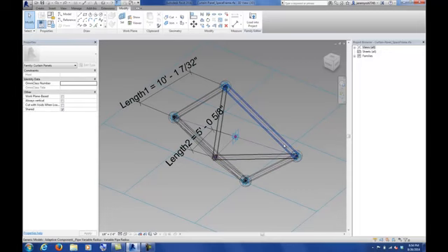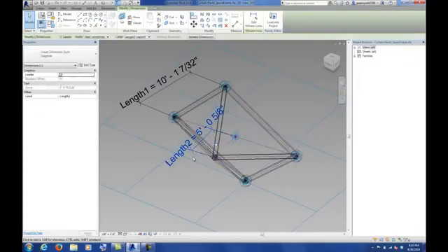All of these adaptive points, 1, 2, 3, 4, were part of this curtain panel pattern-based family. So I can reference those all I want, but I can't create new points, because those are just reference points and they aren't adaptive, and I can't make this reporting parameter work correctly.